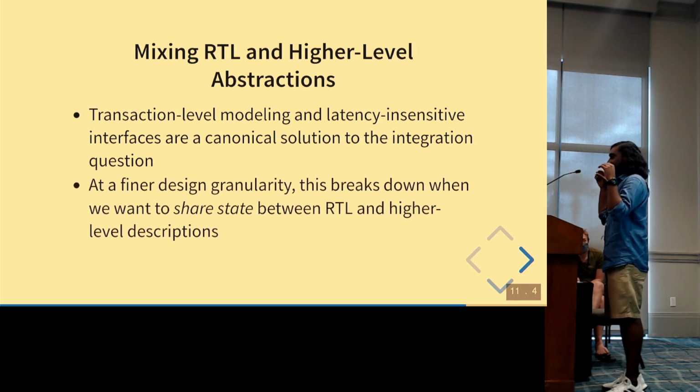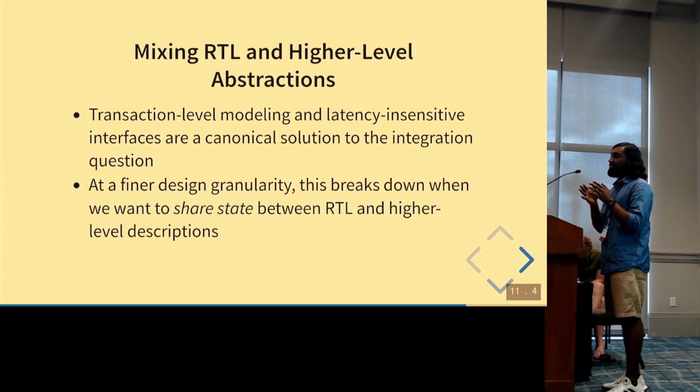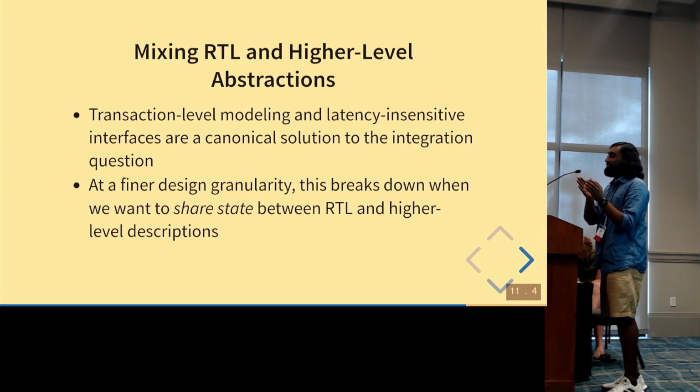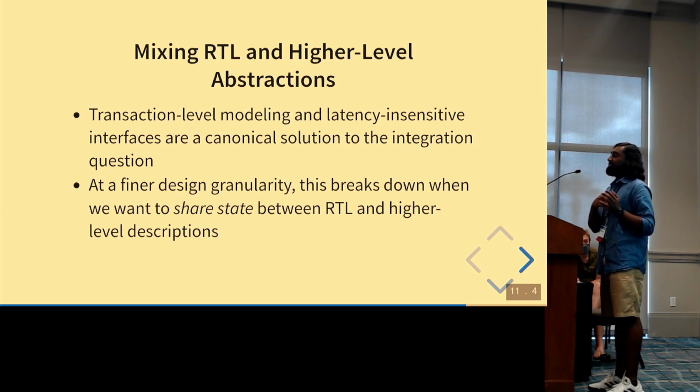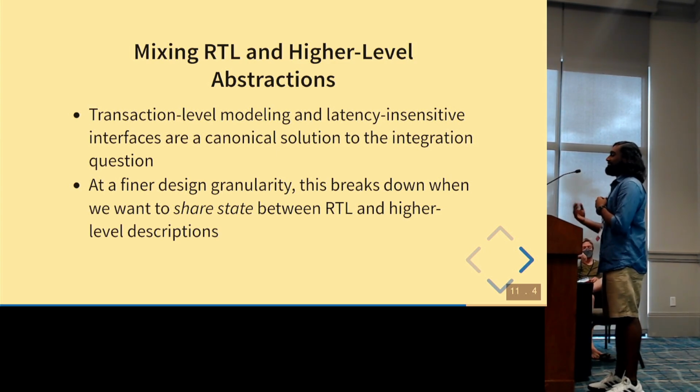But when we go to a much finer design granularity, where we want to use lightweight HLS along with dataflow-type DSLs and RTL DSLs in one module, it becomes very difficult, because typically we want to share state between the RTL and higher-level descriptions. And currently there isn't a good way to specify how to do that.